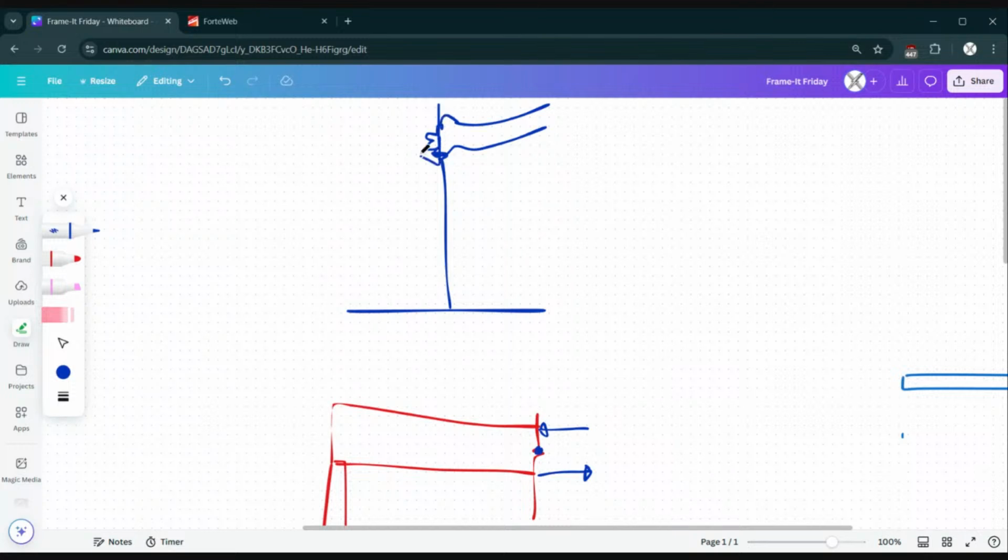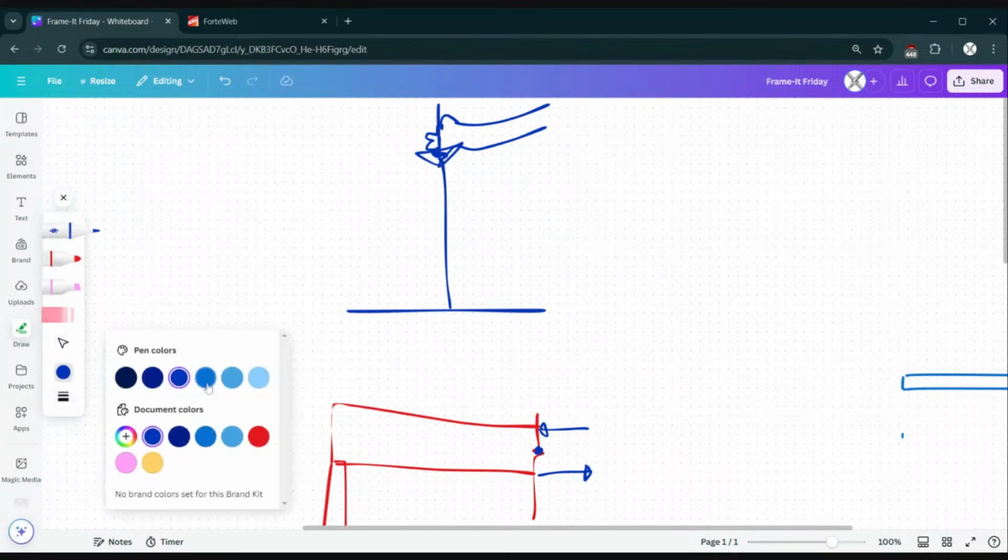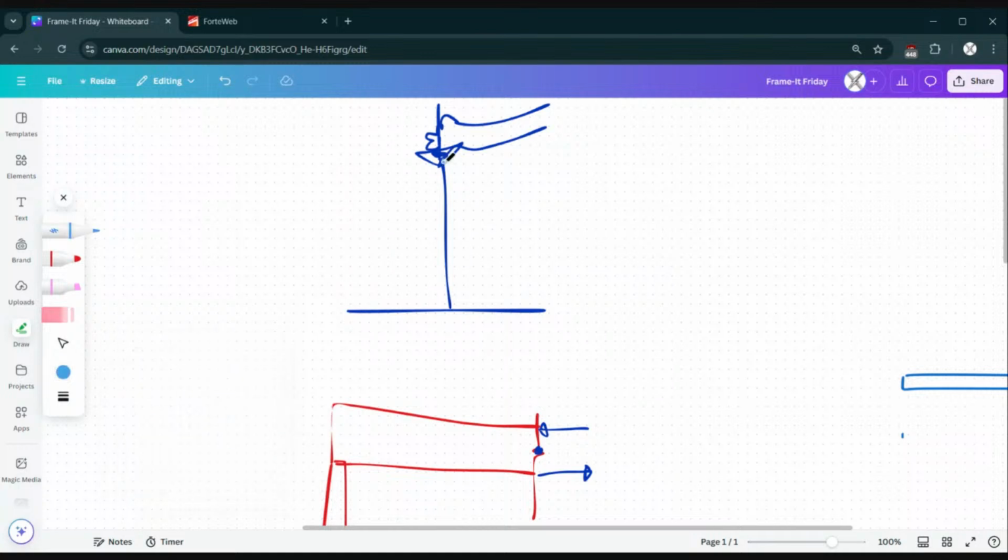But if you were to push down really hard on the ruler, what would it do? Well, it's not going to stay straight up. What it's going to do is it's going to bow like that. That's called a buckling failure. The material can handle the compressive weight of what you're putting on it, but the shape of the material and the length and the slenderness makes it so that it can't take that and it bows out.